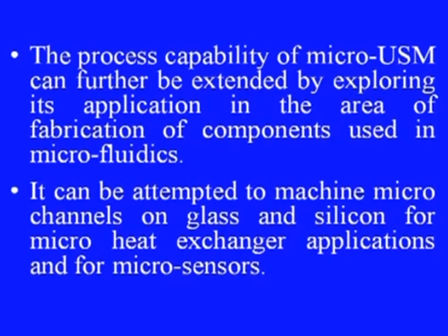It can be attempted to machine micro channels on glass and silicon for micro heat exchanger applications and for micro sensors, which are very important areas as far as micro channels are concerned, and micro channels can be fabricated using micro machining techniques such as micro USM.